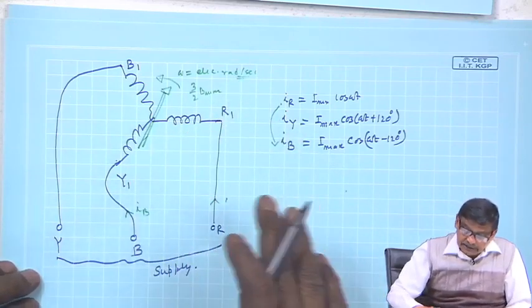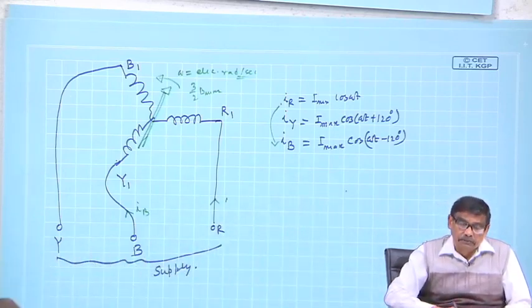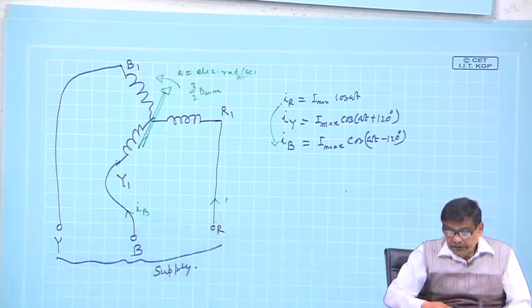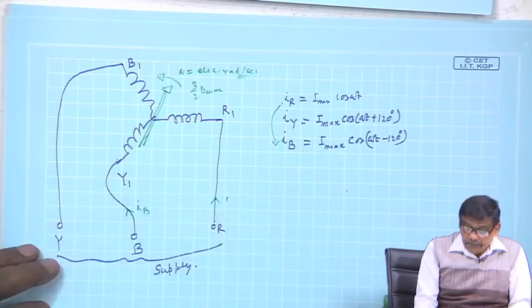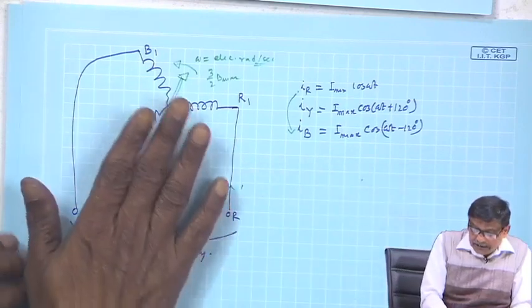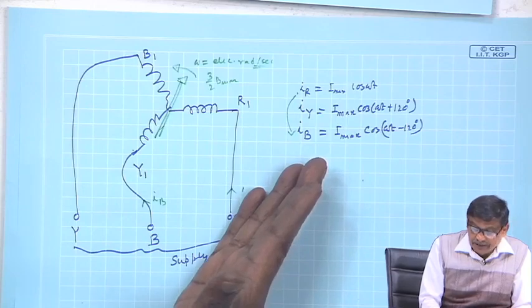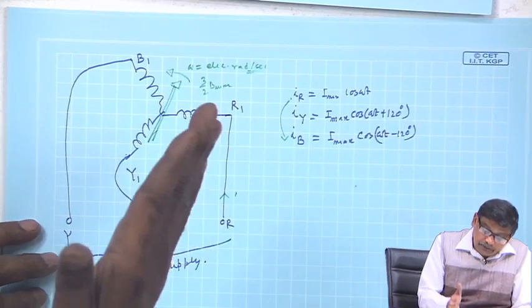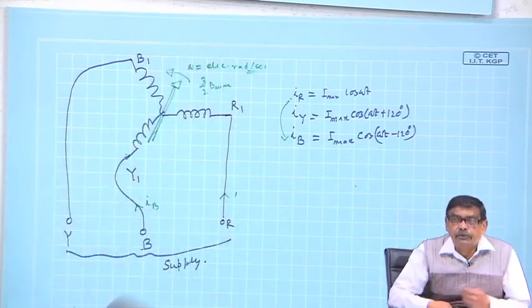So, this actually was first suggested by Nikola Tesla. Before that it was all DC supply and people were doing this, that. Then he told that if you can see, the example is, anyway in the next class I will tell that important thing, but the point is, if a balanced 3 phase winding, the coils are stationary, that is the most important thing, and you have been able to produce a rotating magnetic field without mechanically rotating anything.